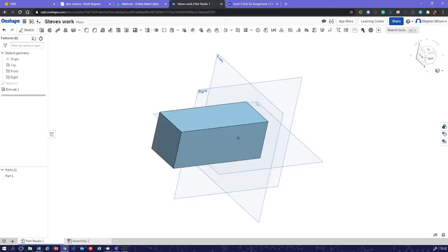As I think I've said before, when I was learning to do this, I was told to be thinking about how you're going to manufacture this. In this case, this isn't a very big part, just over 12.5 centimeters long. So we'd probably make this part out of solid steel bar, and then we'd cut out the material afterwards. We'd take it out with a milling machine. So thinking about that, each cut that we do, each removal that we do here should relate to a machining operation.